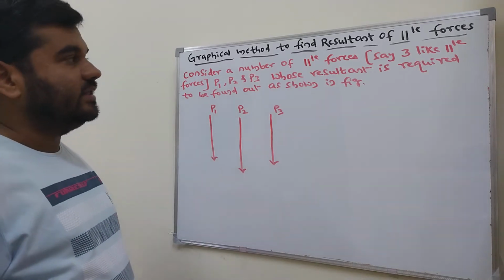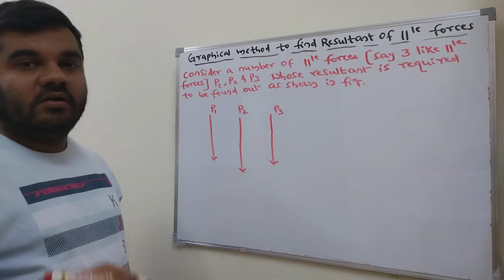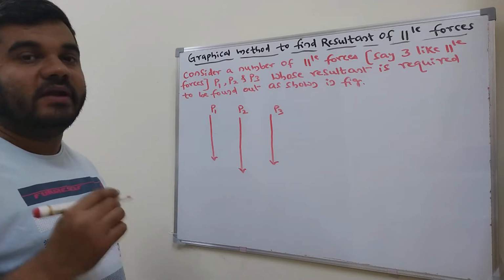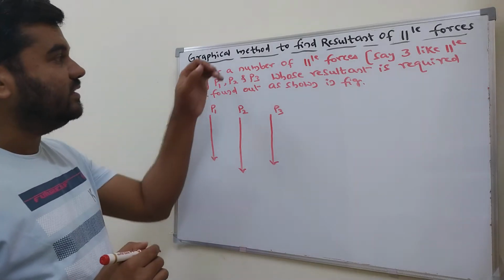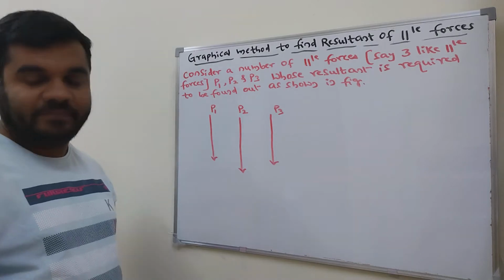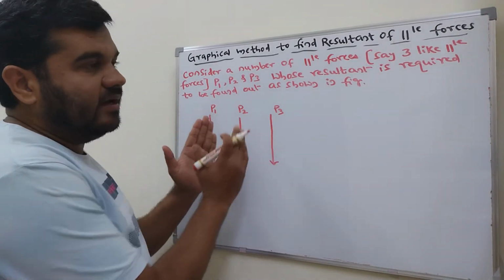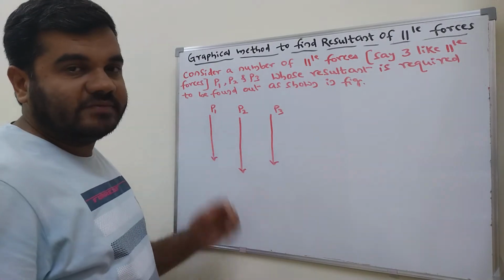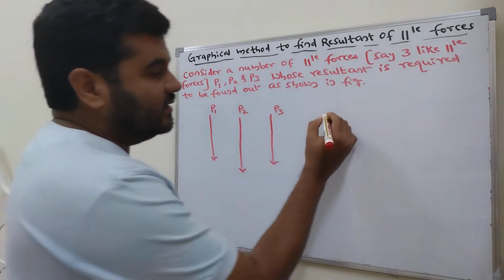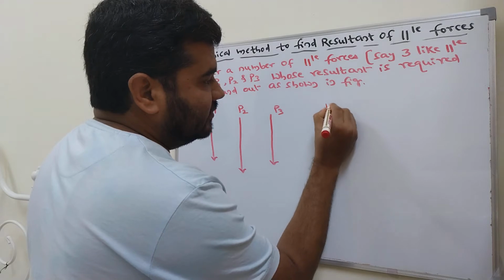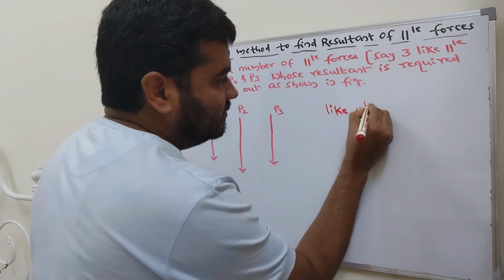Okay, in this video, we are finding the resultant force of parallel forces by using the graphical method. Here, there are two types of parallel forces. One is like parallel forces.